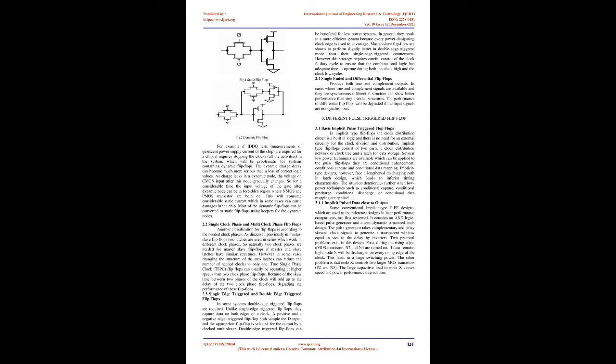Implicit-type designs, however, face a lengthened discharging path in latch design, which leads to inferior timing characteristics. The situation deteriorates further when low-power techniques such as conditional capture, conditional precharge, conditional discharge, or conditional data mapping are applied. 3.1.1 Implicit pulsed data close to output.